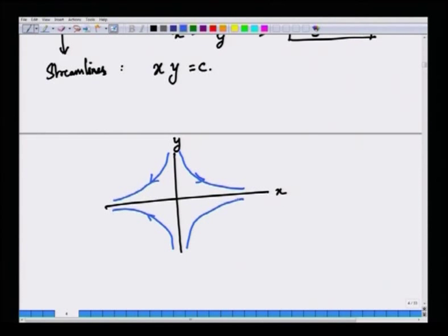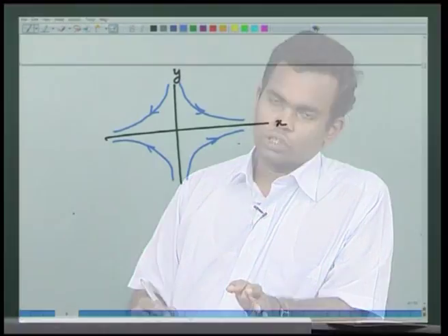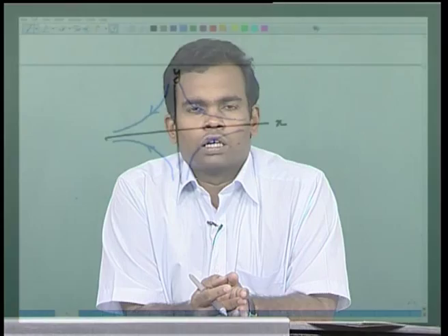Okay. So, of course, we are not worried about how this flow is going to happen here. In the context of kinematics, we are simply trying to understand how to describe flows and motion. In general, we have streamlines, streak lines and path lines. All three descriptions will merge if the flow is steady, but if the flow is not steady, then all three descriptions will be different from each other, and it is not easy to figure out one from the other.